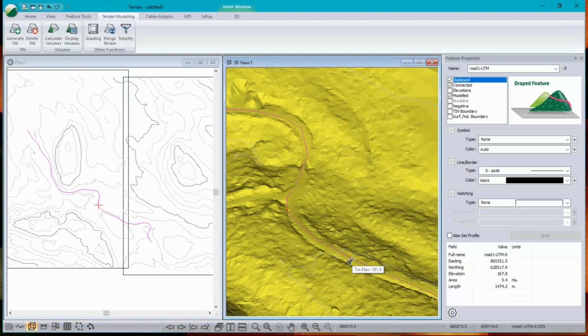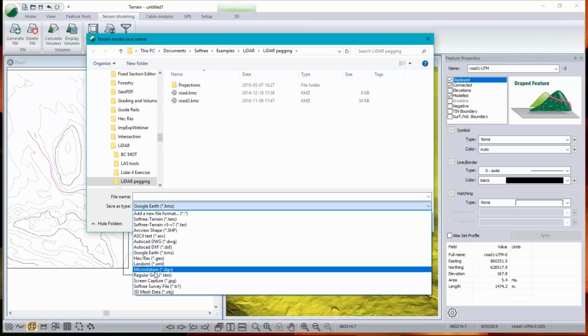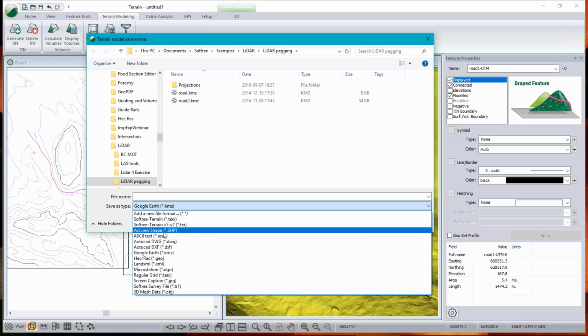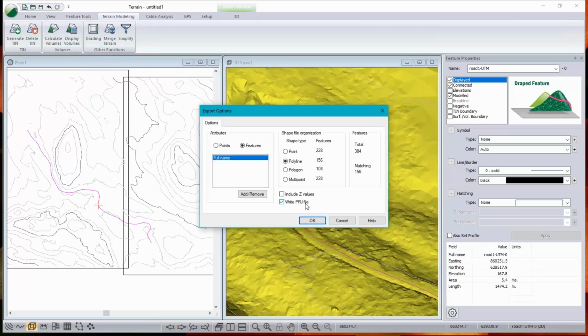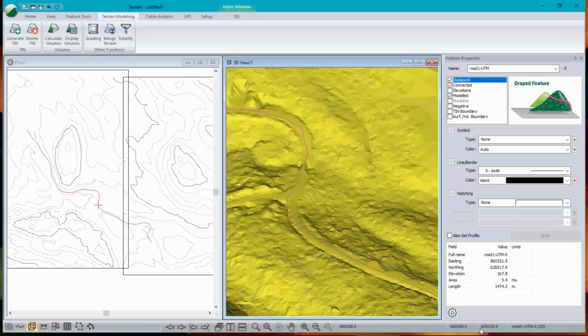And so I know that my 3D data is lined up as well. And everything is georeferenced. And now I can pick in a road, I can draw a polygon, and I can export any of those features back to Google Earth if I want, or bring it into some other software, like, for example, ArcGIS. We do File, Save As Shape. Where is it? There we go. So you can take your line work, you can export it back to shape, and it will create a projection. So that shapefile will be georeferenced, right? PRJ, that will be a georeferenced shapefile.